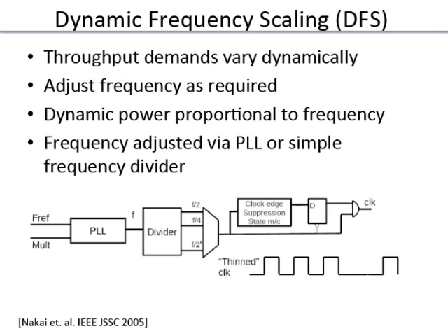But of course, if you recall, for the control of the mux you have to be careful. Think about how you would do the control of the mux so that you don't have false edges coming in. Whatever you looked at for clock gating, you can apply something similar here. That is not being shown just for sake of detail. In addition, these are just divide by 2 ratios. If you want something in between, what do you do?